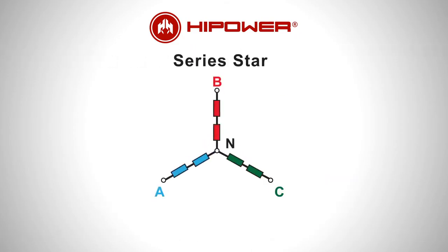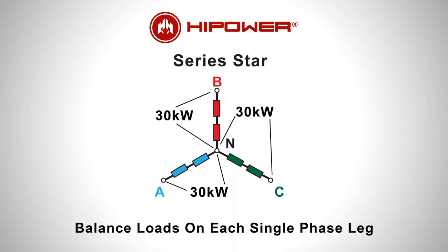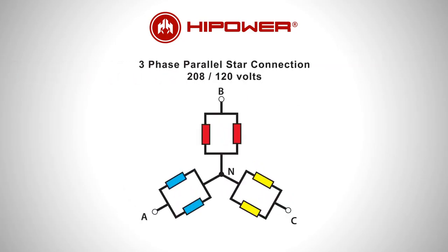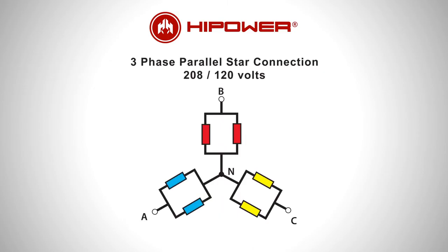Having taken account of the increased load on a generator to start electric motors, the next most important action is to ensure that on a three-phase system, all 3 phases carry an equal balanced amount of the load. A typical three-phase generator connected here in a parallel star three-phase 120/208 volt arrangement allows for the connection of single and three-phase motor loads.